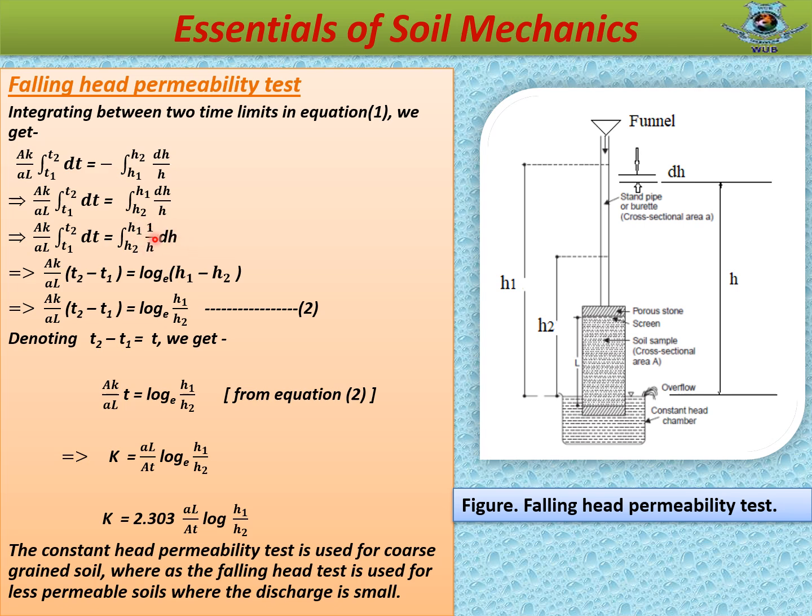By integrating, we know the integration of dt within time limits t1 and t2 is t2 minus t1, and the integration of 1 by H dH within the heads h1 and h2 is log e h1 by h2.